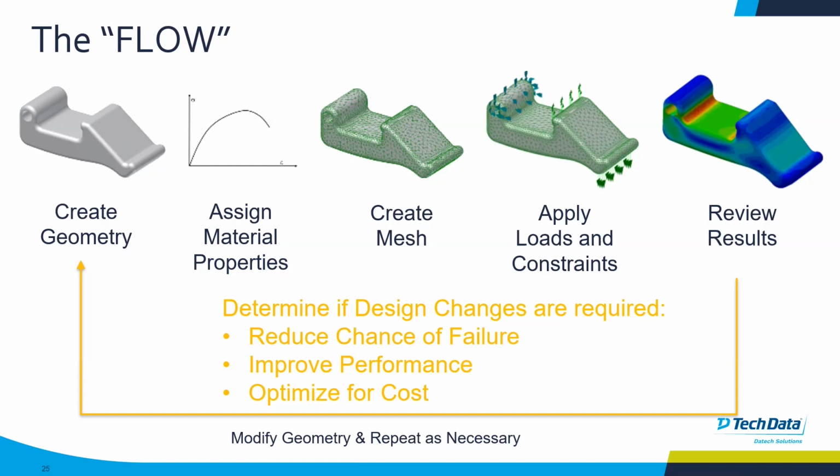Create mesh. Mesh settings are also important. Apply loads and constraints. This is also very important because loads and constraints come from the engineer, the user or the operator who runs this analysis. So getting the loads information especially is very, very critical. And then specify constraints.